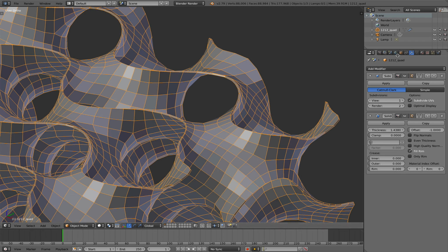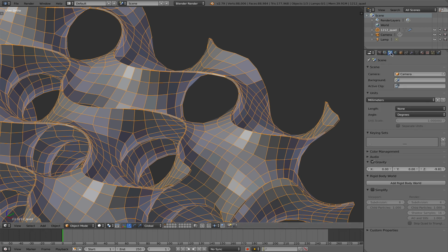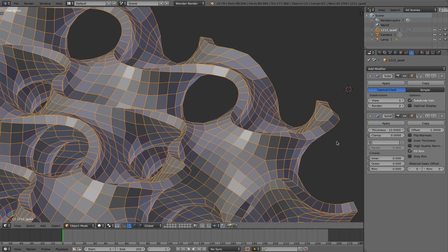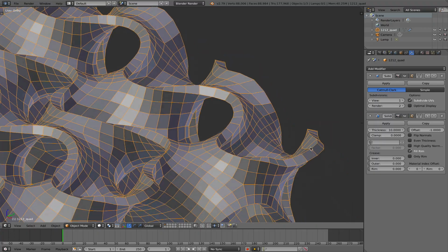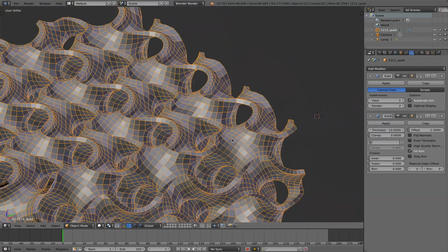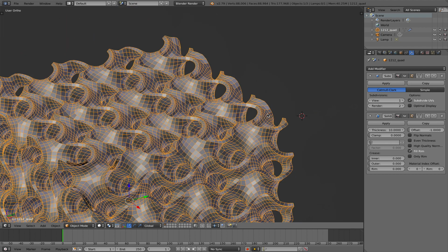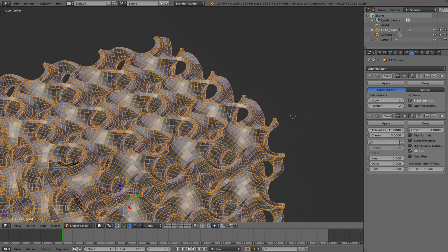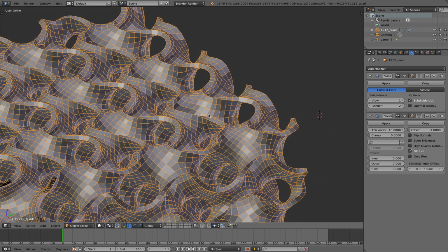So before I do that, I'm going to switch, and the units are already set to millimeters. That's good. I'll go back to my modifier stack here and increase the thickness to 10. So now it's 10 millimeters thick. That means that's the distance between the T-spline faces. That doesn't necessarily mean, if you don't have enough geometry in your mesh, that the thickness of the final body will be very consistent. It will be fairly consistent with the surface density now.